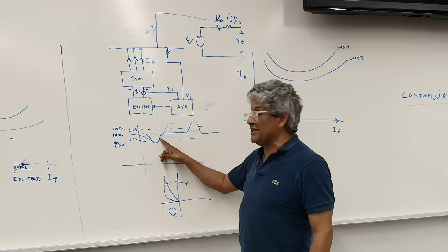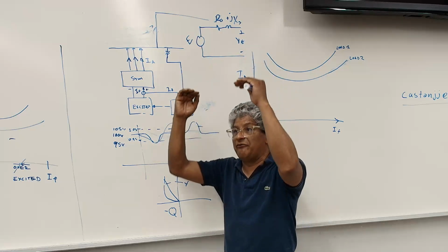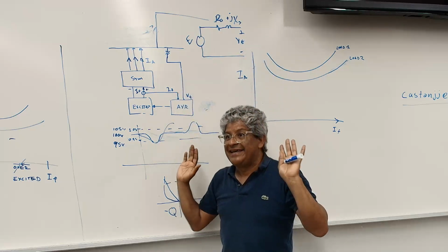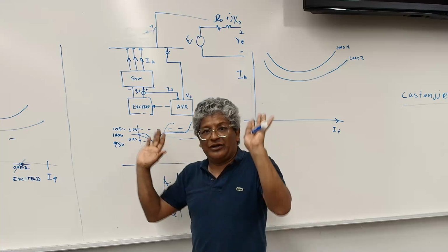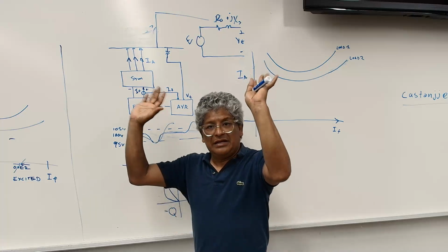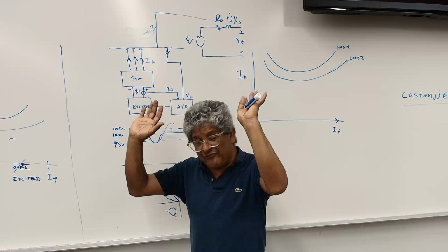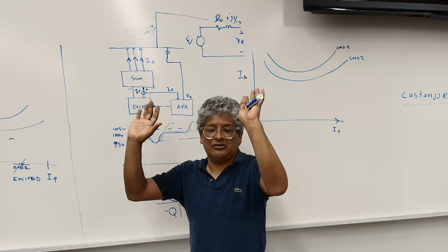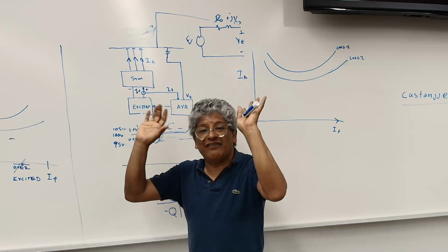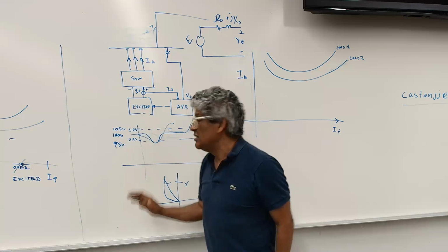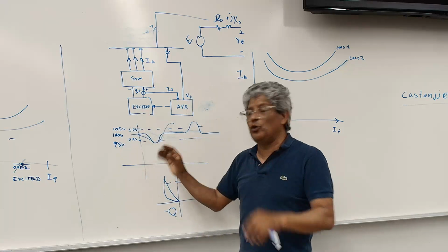So you have a fault, and that's what I'm saying. When there's a system fault on the voltage on the grid, those synchronous machines will try to hold it up, right? Hold it up, hold it up, hold it up. And they're very good. They're very strong. The reason is because they have a lot of inertia in them, right? To keep the VARs flowing.